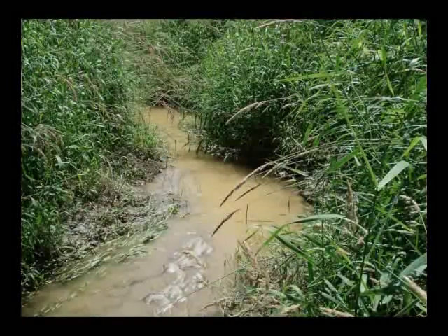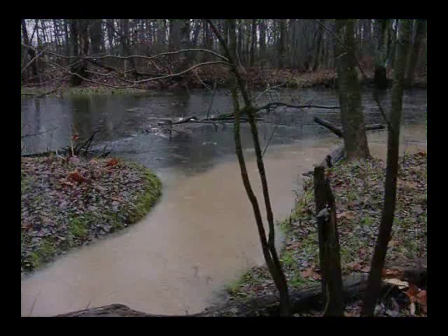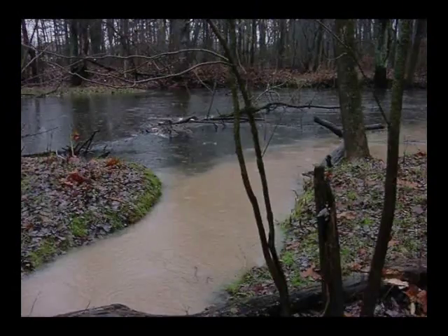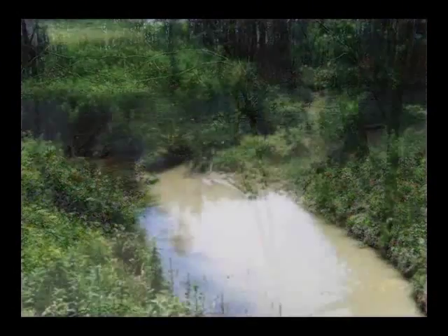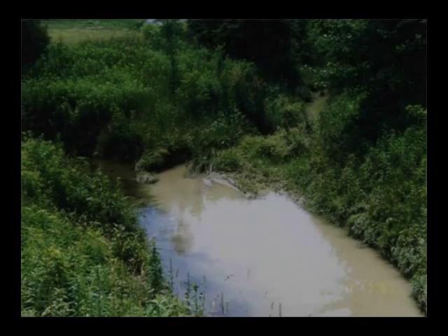Unless properly planned for, the increased runoff may flow onto adjacent properties or into our lakes, rivers, streams, and wetlands. Sediments or other pollutants are also carried along with the runoff to the adjacent properties or surface waters. The volume and rate at which stormwater is discharged from the site must be considered prior to undertaking any earth change activity.